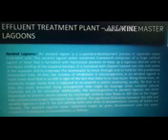Air is blown in the form of a stream of bubbles at the bottom with mechanical devices for about 2 to 6 days. During this time, a healthy flocculent sludge is formed which brings about oxidation of the dissolved organic matter, and biological oxygen demand removal of the order of 90% could be achieved with the effluent operations.